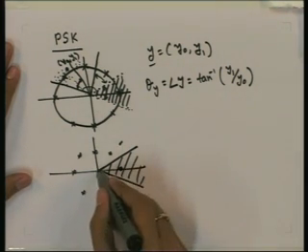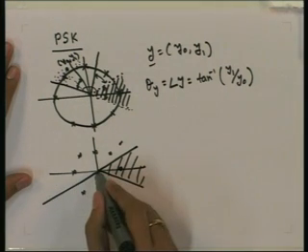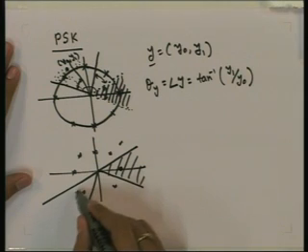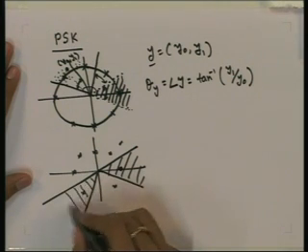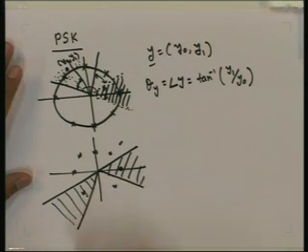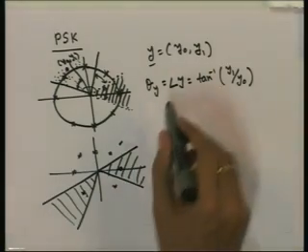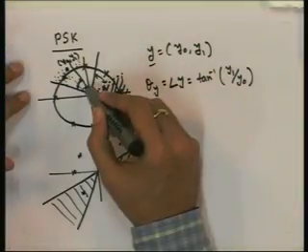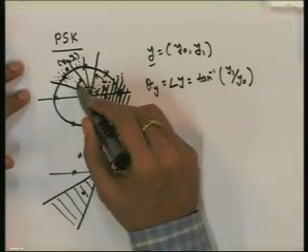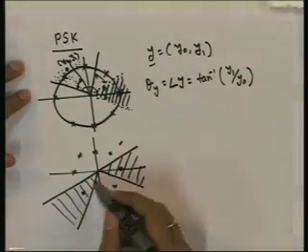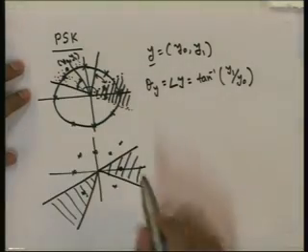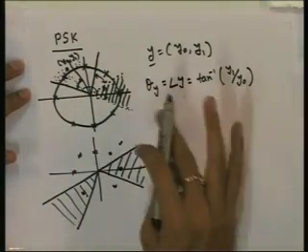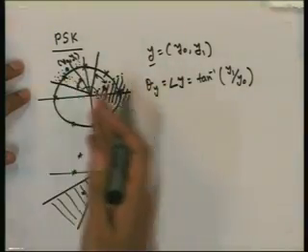Similarly, for this point, this region is called the decision region of this point. So, by finding the phase and then comparing this phase with these decision regions, we can find out which point is nearest. So, this is simpler than finding the correlation and all. Just find the phase and see in which region it falls.